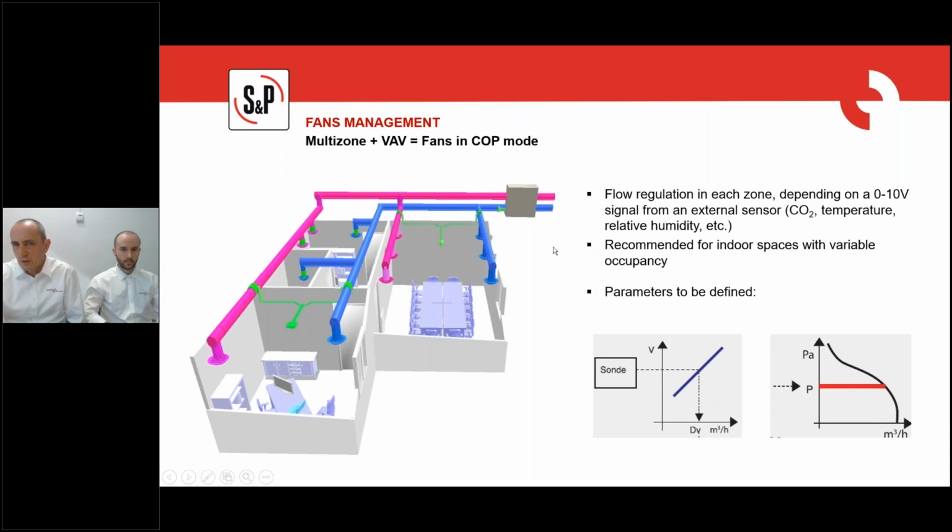Let's say one pressure transmitter, which has to be fitted in the pressure net where we want to detect the value of pressure. It's important to remark that we can select only one pressure transmitter. So we have to decide where we want to place the pressure transmitter, in the supply or the extract side.